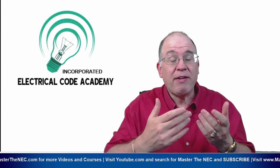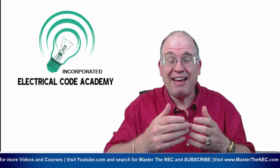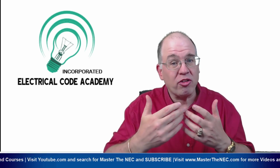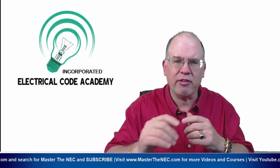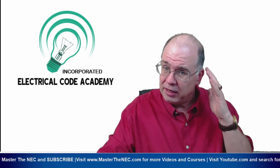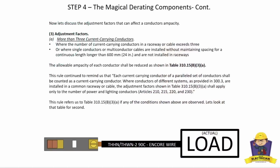Now, even if I have a 4-wire 3-phase Y system where I have a lot of nonlinear loads, then you're going to have harmonics and you're going to count that neutral as a current carrying conductor as well. So just keep that in mind how you count it. We're going to cover that in the presentation, but I just want to throw that out there. Hopefully that's not way over anybody's head at that point. We're just laying some groundwork is all we're doing.